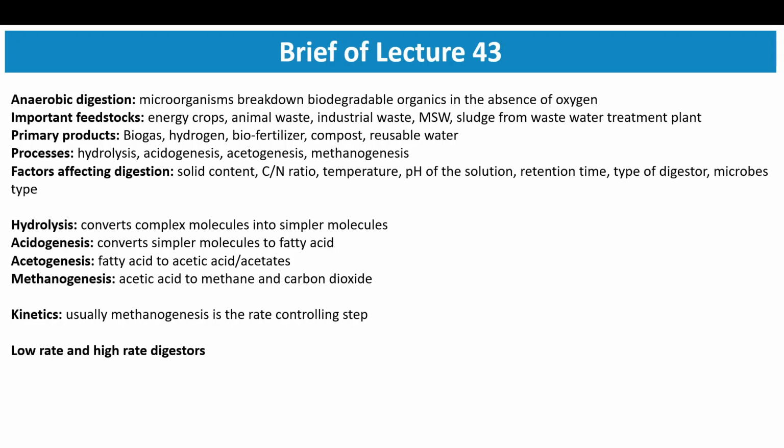this lecture talked about the digestion or degradation of these solids, which is anaerobic digestion. Anaerobic digestion, as the name suggests, requires microorganisms to break down biodegradable material, and as the process is anaerobic, we do it in the absence of oxygen.